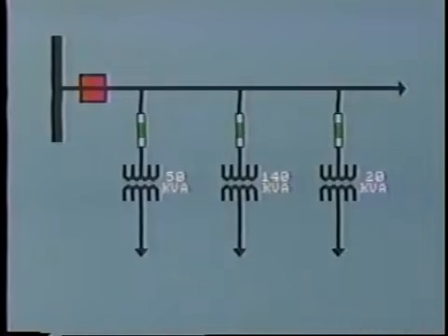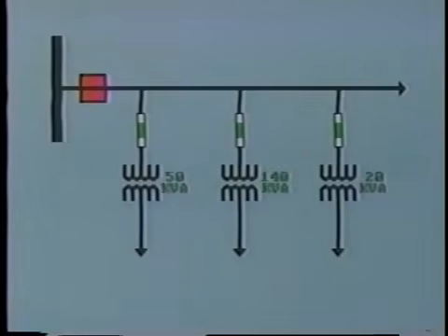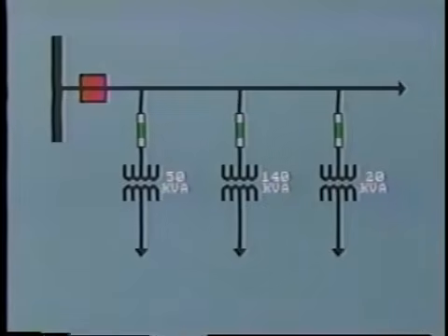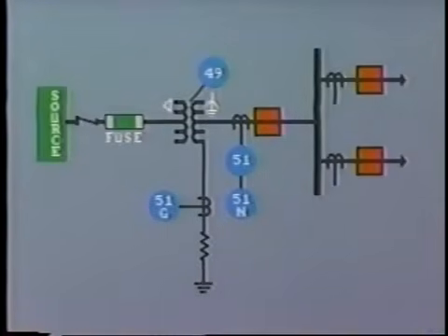On smaller transformers, it is usual to omit the primary side breaker for economic reasons. Typically, we may have many large and small distribution transformers tapping off a distribution feeder. The feeder will be fed from the substation bus through a breaker. But each distribution transformer will be protected by high voltage fuses only. Here is a typical protection arrangement for a distribution transformer feeding a small industry.